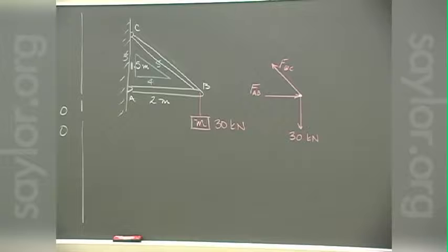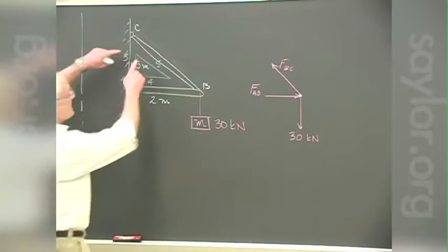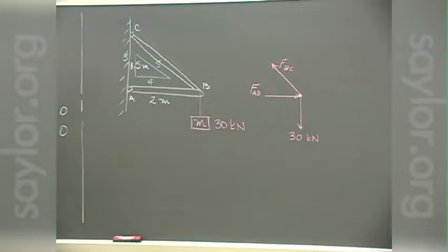Well, why are they in the same directions? Two force members. Both of these, the two structural members, AB and BC, are both two force members. Therefore, we know immediately that the forces lie in the same direction as the members themselves. Well, more specifically, in the line connecting the two pins at either end.